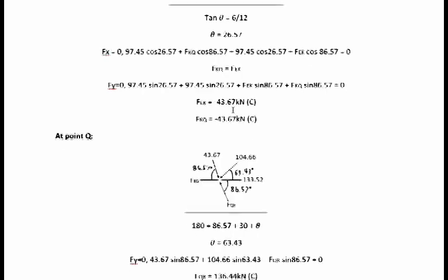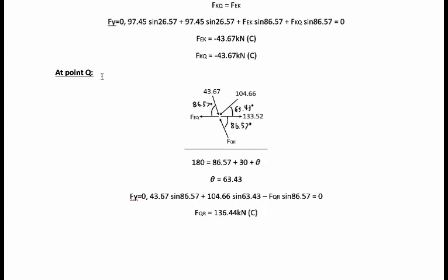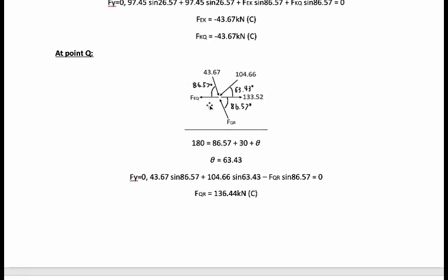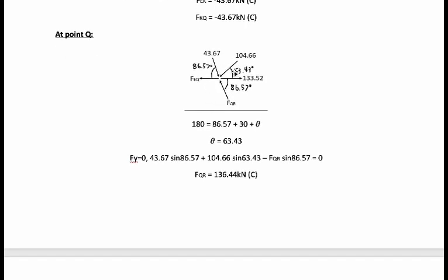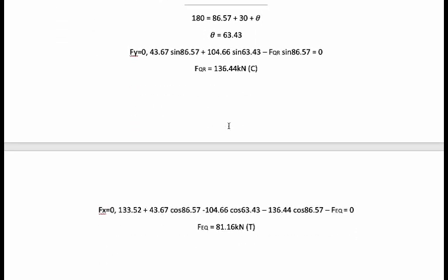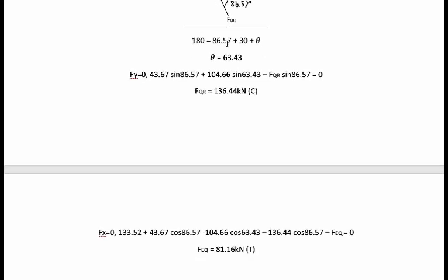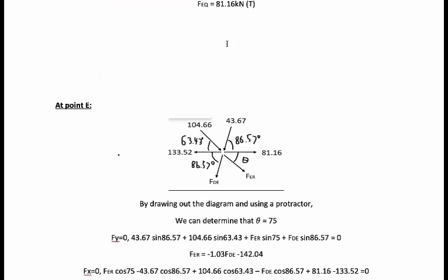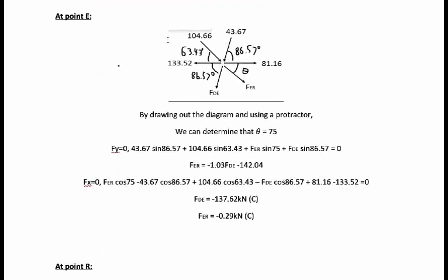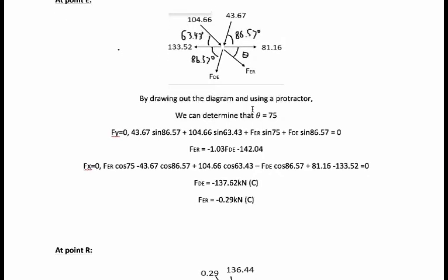We got this answer. Also at point Q, we do the same, we draw the free body diagram, and it's all compressive as shown, the forces, except for force QR it's compressive, but EQ here it's tensile. And lastly, point E, we draw the free body diagram, and we can determine that